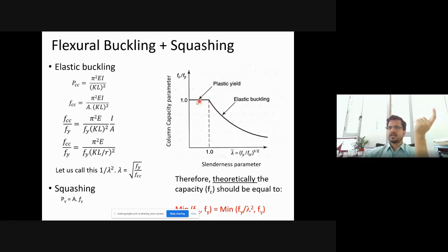We are saying that the entire cross section is yielding exactly at a particular point. So up till that point, up to this level of stress, nothing has yielded, and suddenly everything has yielded. So we go from 0.99999 Fc by Fy, nothing has yielded, and exactly at 1, the entire cross section has yielded. So there is an assumption here, because if the residual stresses were present, this would not happen. This will be a more gradual process. That is one assumption we have made.